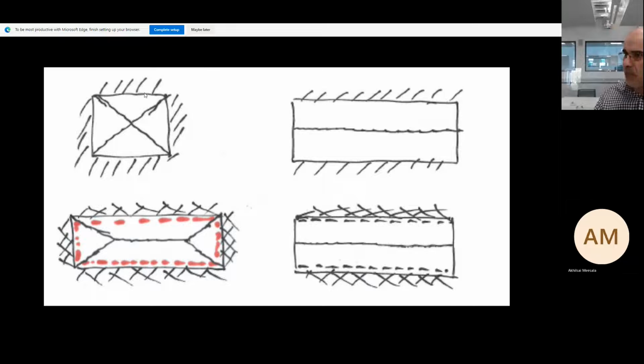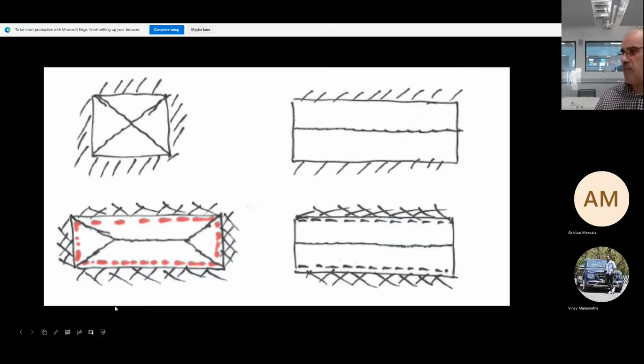The same applies to the square slab: the maximum curvature is in the center. This is where the yield lines will start, and then they propagate and spread to the intersection of the axis of rotations, the edges here.